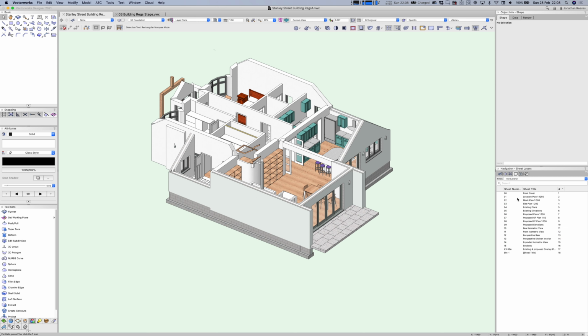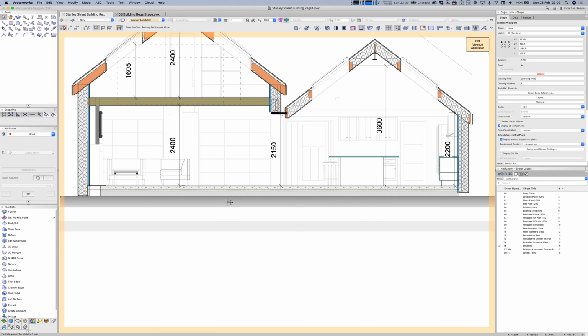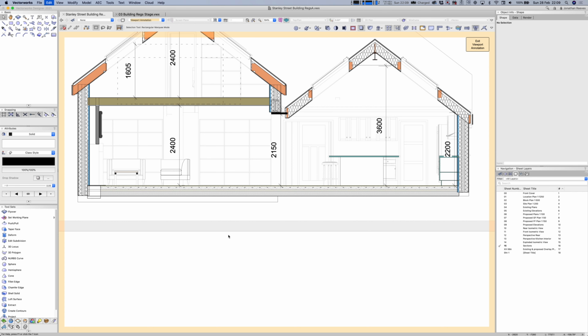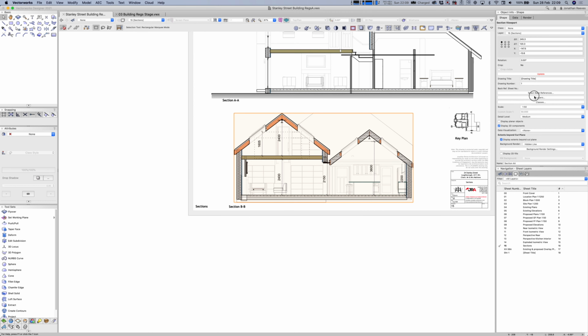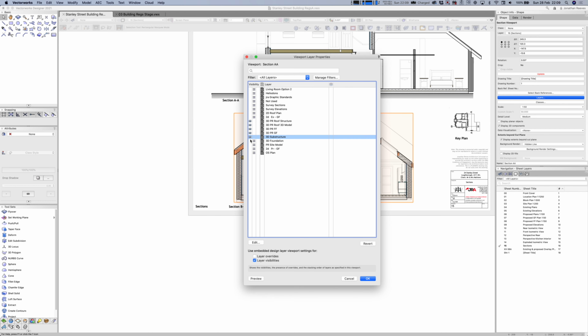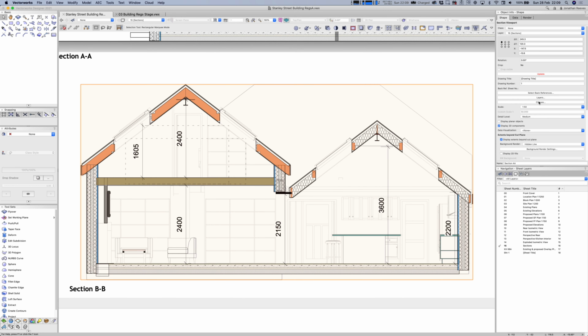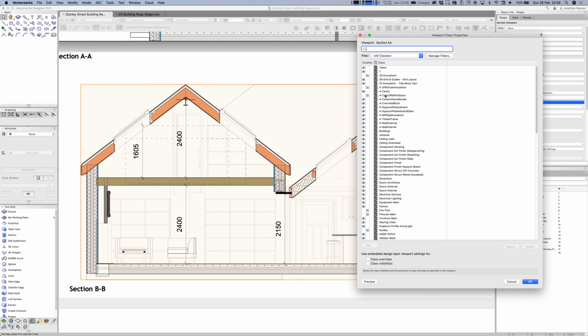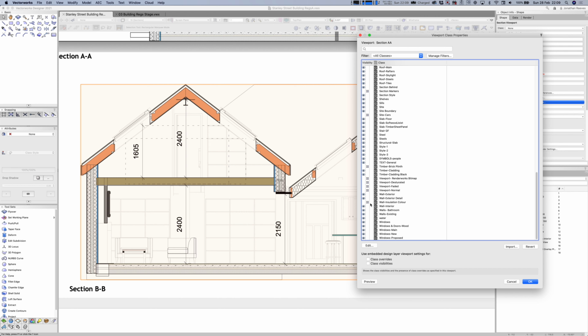Okay, good. So let's have a quick look back at the sections. So we're going to go to the annotations. I'm going to delete basically the grey fill that I just placed below for my planning drawings when I wasn't worried about the construction or showing the foundations on the planning drawings. And all I need to do is basically update the viewport to allow for both the new classes, but also tick layers to update the foundations and the substructure.